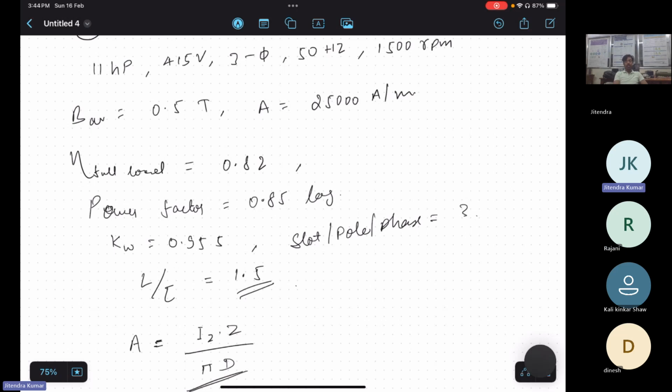Yes, you are close. Then we can calculate the current from there. P equal to 2. See, you are given the voltage rating, right? 415. And in voltage, is there any number of turns expression there? Recall carefully. In induced EMF, is there? Yes. Number of conductors is directly proportional, right? So 4.44 into f into phi into Z.